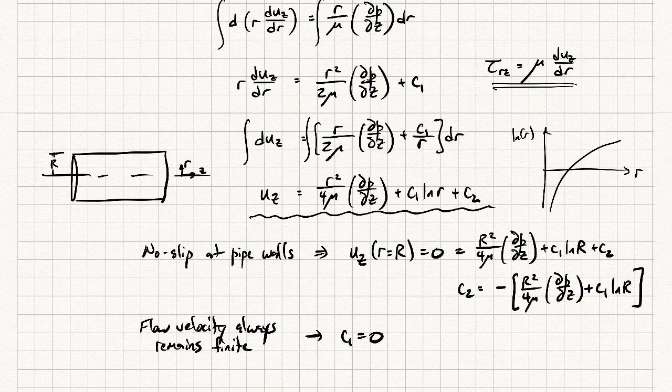If you look at this pipe, you might realize that the velocity profile should be symmetric. Because it's axisymmetric, let me just sketch this out, there's no reason you should have a peak to one side of the center line or to the other side. There's no preference for that because of the symmetry of the problem. So you would imagine that there would be an inflection point right at the center line. Either the velocity is a maximum at the center line or it's a minimum, but nevertheless there's an inflection point right at the center because of symmetry.